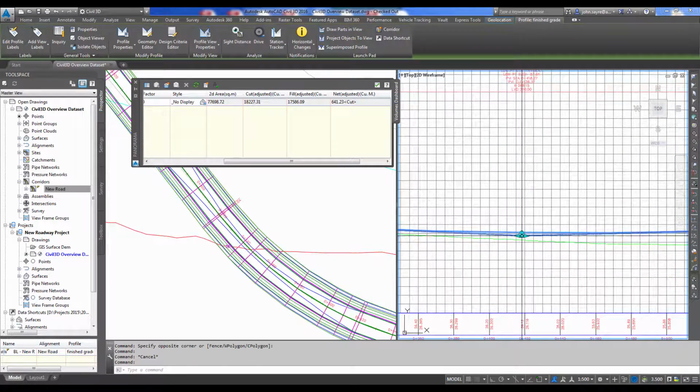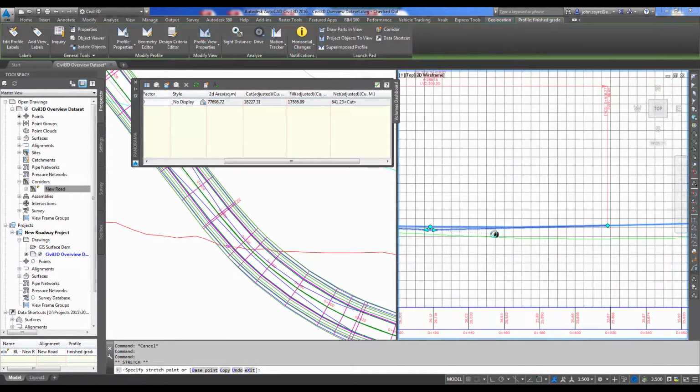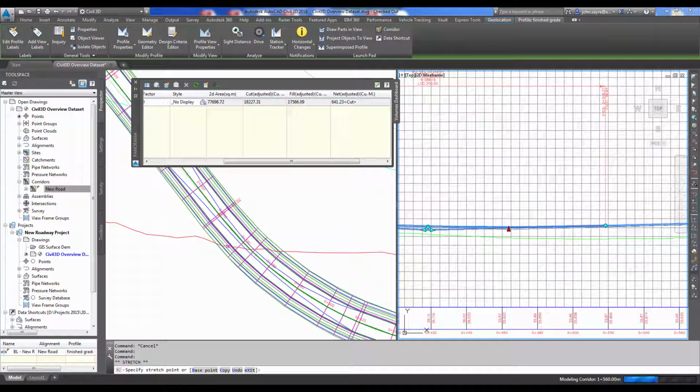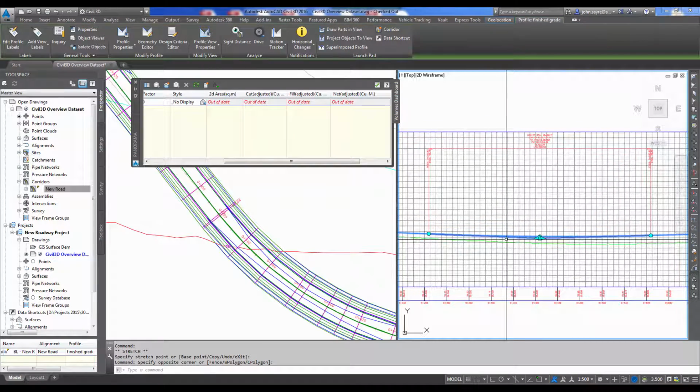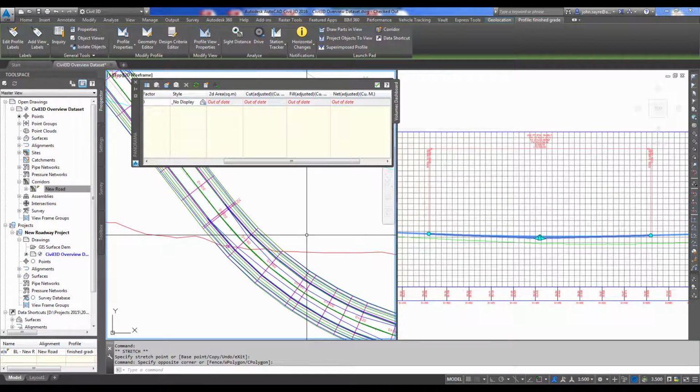So I'm going to select that vertical curve, and I'm going to move the low point to this location right here, down further so we've got a little bit more area to get underneath the road and daylight on either side. So you can see it adjusted the corridor information, plus it adjusted the surfaces, okay, just from that one grip edit. So when you think about minimizing errors and rework, this one adjustment touches a lot of different entities inside of Civil 3D. And if you can imagine trying to make sure that the labels match up and have been adjusted accordingly, this is a big help.